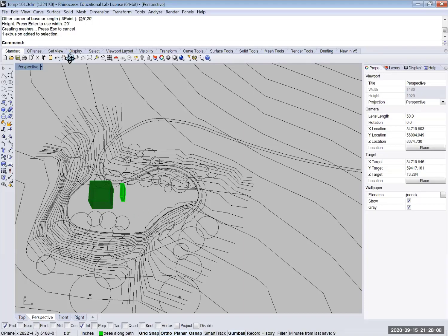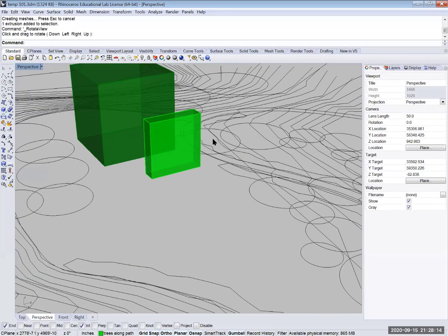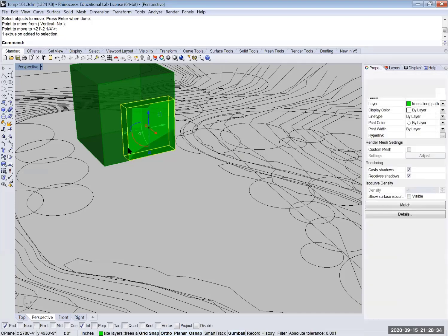I'm going to go ahead and place this thing. So here it is. I'm going to zoom in here. And the first thing I'm going to do is move it from that intersection point to that intersection point. So it's right there in the corner. Now, I read my prompt, and my prompt says that the floor is 3 feet above grade. So that means I've got to take this porch so that I'm not creating a subterranean or below floor level porch. I have to bring it up 3 feet.